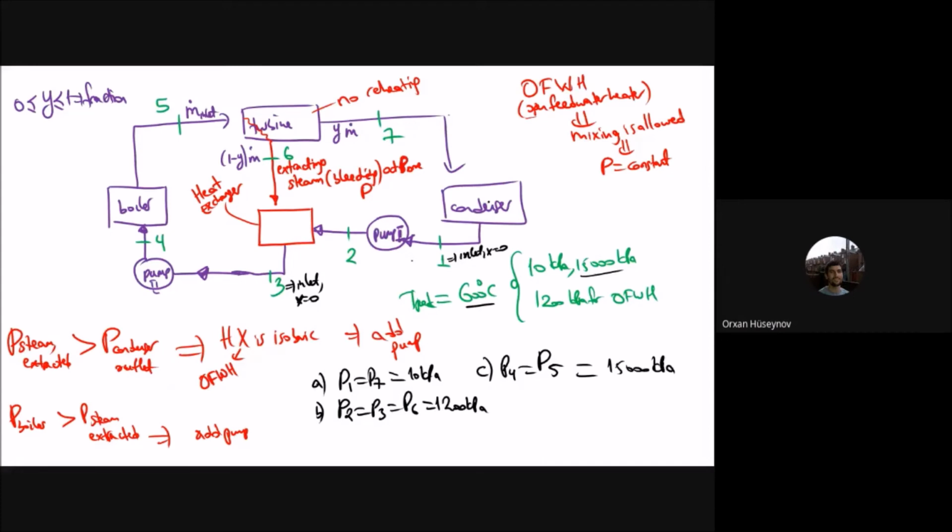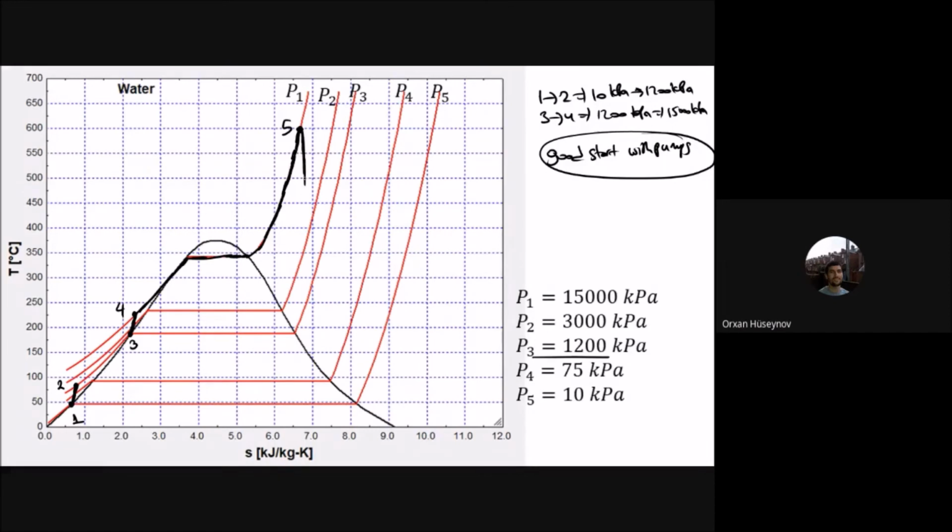7. This is the condenser. You can see that it drops from 5 to 7, and this 7 is at 10 kilopascal. Okay, so I should go from 5 to 7. And this is point 7. So I have done that part, and now it goes from 7 to 1, and this is the condenser. Let's do that. This should get the isobaric line here. And the 7 to 1, it is the condenser. So I will have that chart, and this one, and that one.